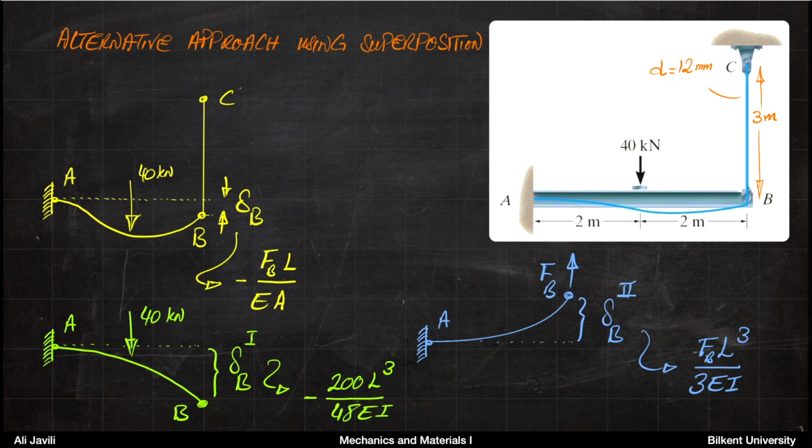The second system would be a beam under a force of FB at the end. And for that system, you can also calculate the deflection at point B, which is this. Now, the deflection of the point B itself is minus FBL divided by EA. And the minus comes just from the fact that if delta is larger than 0, so if delta is elongation, your deflection of the beam would be negative.